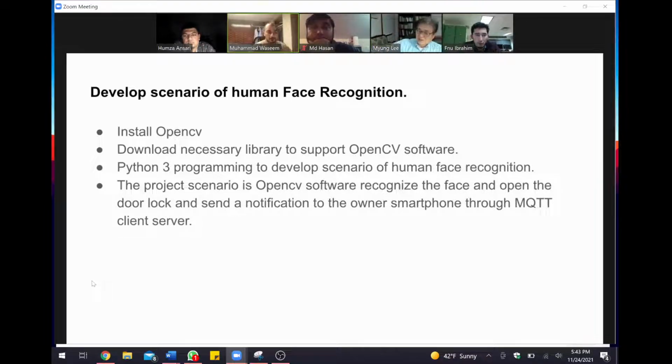The Pi already has the intelligence there, right? OpenCV and TensorFlow are there, so you can train, and then the output will come from there, and then you communicate. So let's say they detect something using TensorFlow, and then using MQTT they communicate with the other board, like the ESP32.